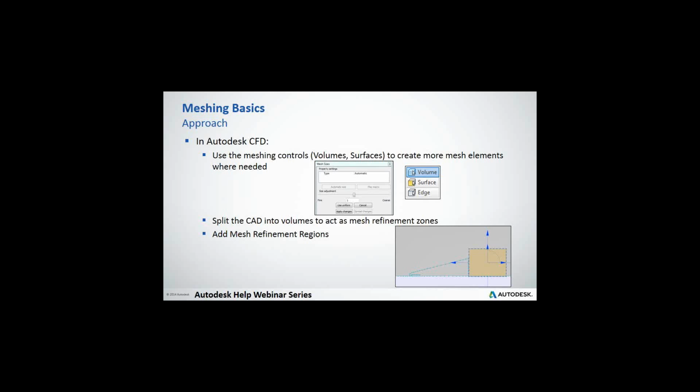I used one recently. I used a diamond underneath an internal fan that was blowing air down into a huge garage area. I didn't necessarily need it to be uniform because that would have been way too much mesh, but I did want to tighten it up so I could see basically the fusion of air and capture that.